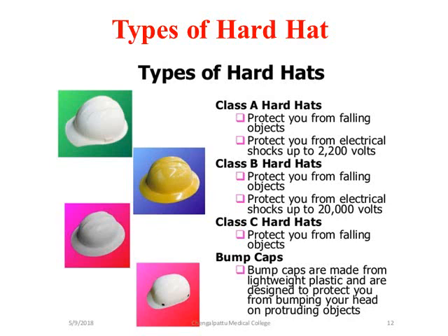They also provide protection from impact and penetration hazards by falling objects. Next, we have the class C hard hats. They are lightweight, and as they are lightweight, they are more comfortable when compared to class A and class B. Of course, they provide protection from impact. But we should remember, class C hard hats won't provide us protection from electrical hazards.